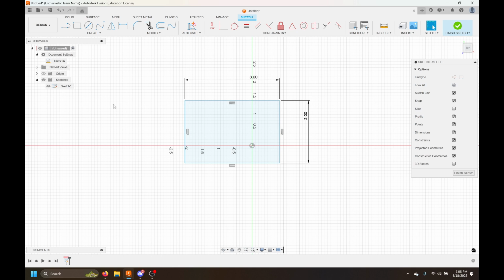Did you find the tool? Yes. Okay. It's full screen. What are we doing this in, millimeters or inches? Inches. How do I change it? Oh, so you go to document settings. Okay. Drop down. Oh, you hit finish sketch first. Then go to document settings. Hit Units. And then you change it to inches. And then double click your sketch. Yeah, now you can.